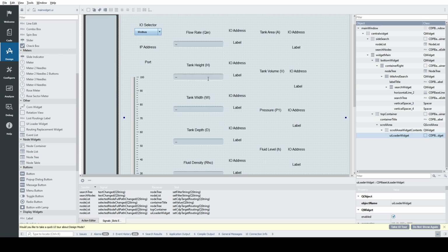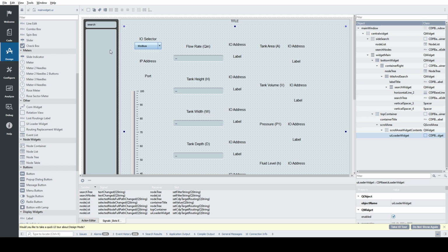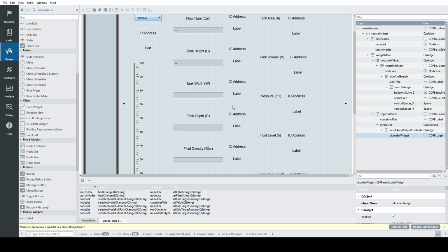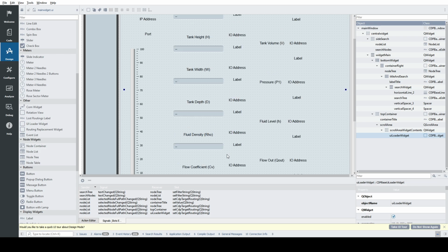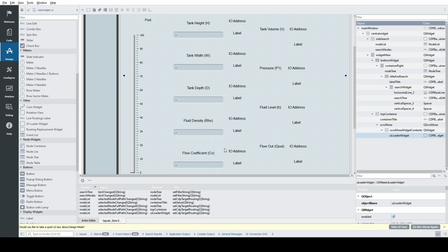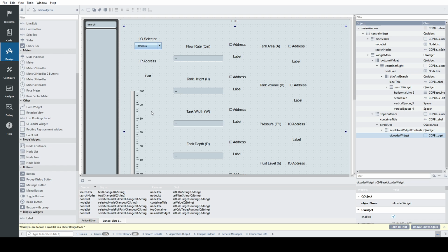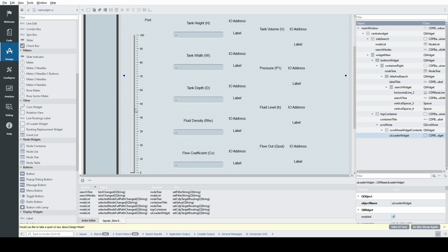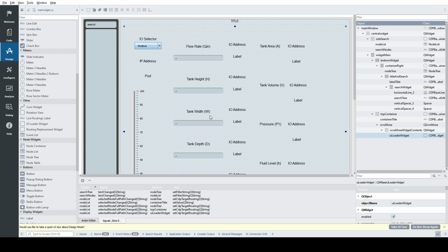this HMI, what it does is, if any user is connected with this HMI through web, that user can change the value of Q in valve, Q in flow rate in. You can change the value of density as well, Q out as well. On the basis of that, the fluid height value in this tank will change.